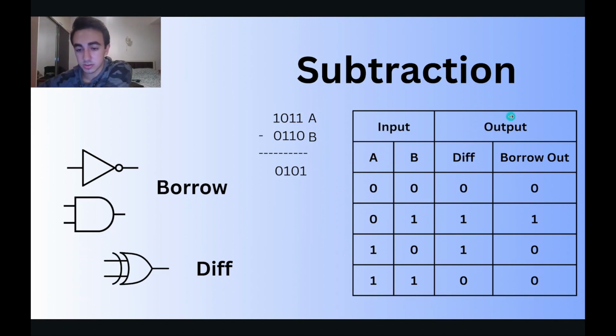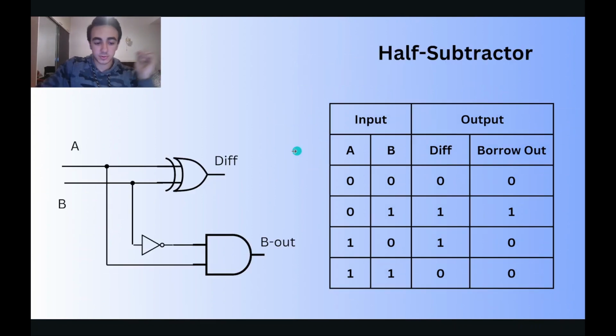So, for example, we can negate the first input. We will get 1, 1, 0, 0. In this case, this would be something similar to an AND gate, because 1, 0 outputs 0, and 1, 1 outputs 1. So here we negated this one. And so this is 0 and 0, the AND gate outputs 0. And 0, 1 also outputs 0. So perfect, we already know the logic for this. So let's perform it.